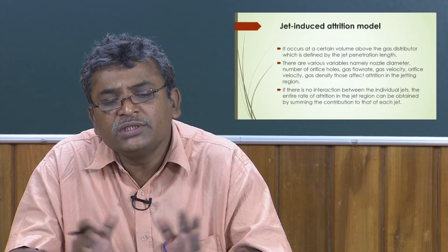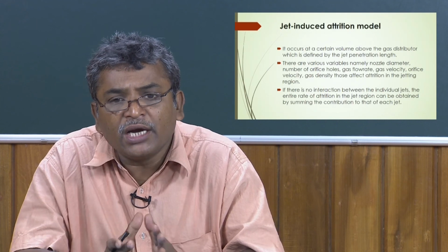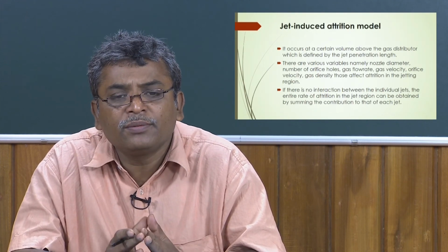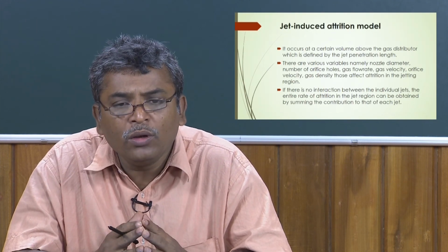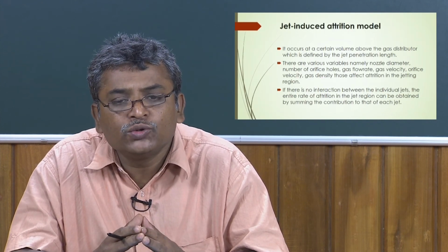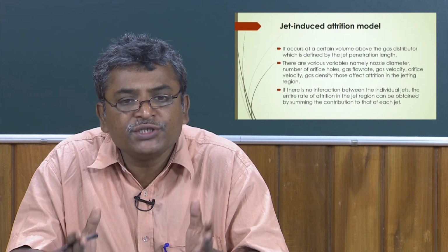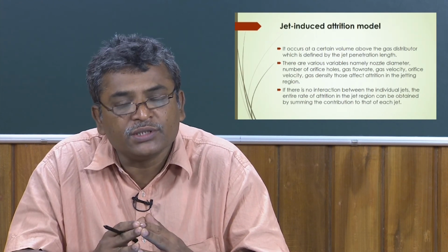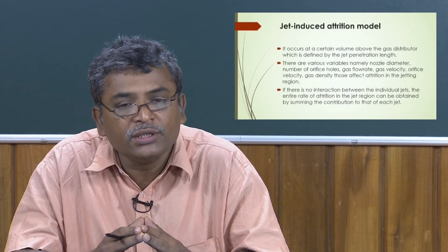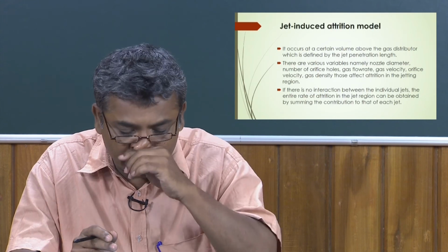Also, sometimes if the interaction of the jets is there, the energy coming out from that hole as a gas jet may change the energy distribution in the fluidized region, and because of that the attrition rate will change.